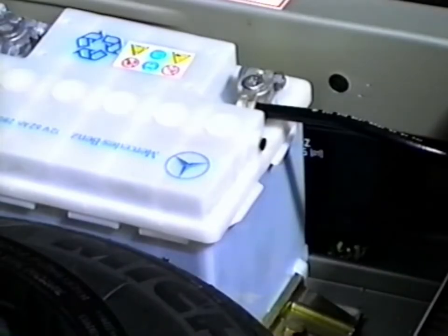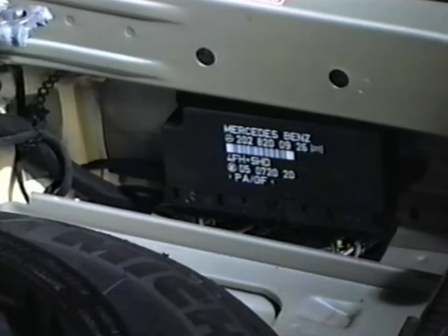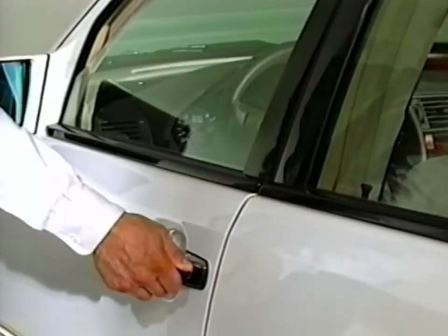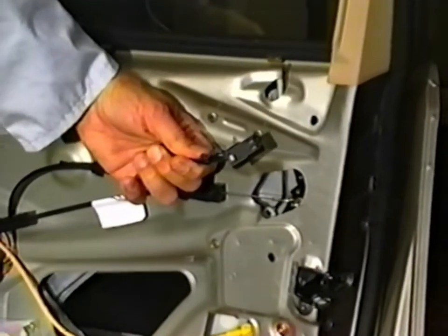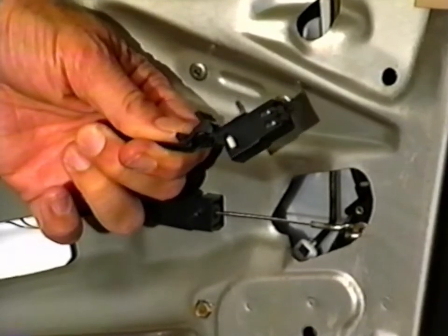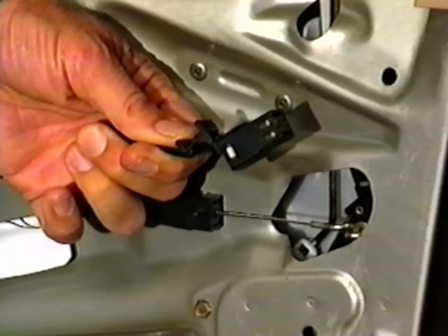The convenience control module is located in the trunk behind the battery. It provides one-touch opening of the windows at both front doors and closing of all side windows and sliding roof if the key is held in the locking position. Unlike Model 124, the convenience feature is electrically independent of the central locking system since 2 wires are used on the micro switches for providing the opening or closing signal instead of the previous single wire.